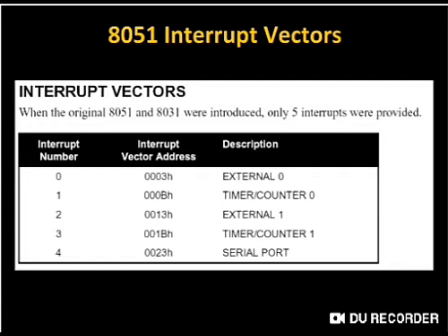These locations are provided to put only the minimum instructions, such as LJMP. If you see the difference, from 0003H to 000BH, only a few locations are there. You have to use those locations either to redirect the program to a safe location and start writing the program there. So this is a very important vector table that you get, and you have to use these addresses only whenever you are writing an interrupt service routine.